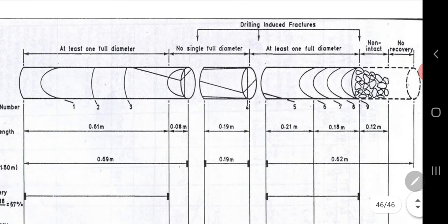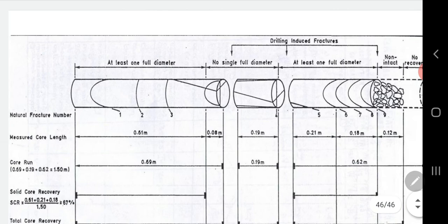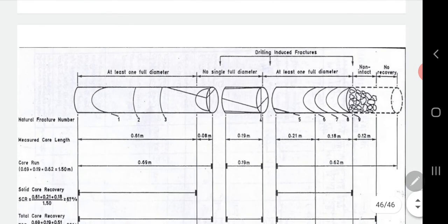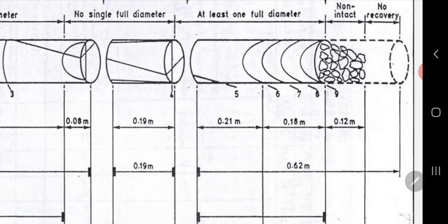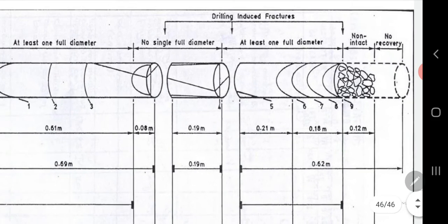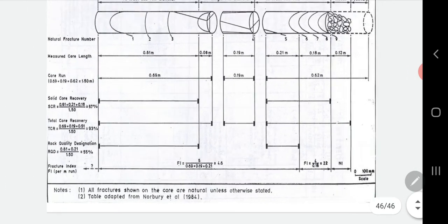When you do the borehole with casing and drill the earth crust, you will recover some sample, and if you get 100% recovery, that is very excellent. But if you see some features or cracks, or some deformation on the surface, that is not a good quality rock sample.